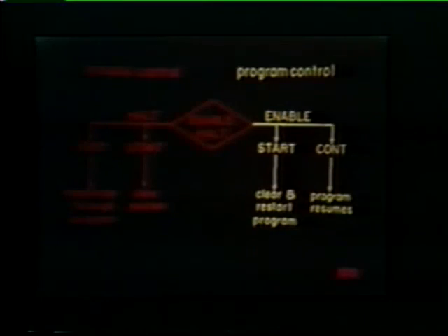Additional information on the PDP-11 consoles can be found in the workbook for this unit and in the PDP-11 processor handbooks. One of the switches we talked about is load address. As the prerequisite for the deposit, examine, and start functions, it plays an important role in console operation. Deposit and examine are used to place information in memory or a GPR and then read it back for display on the console. The start switch function depends on the position of another switch, enable halt.